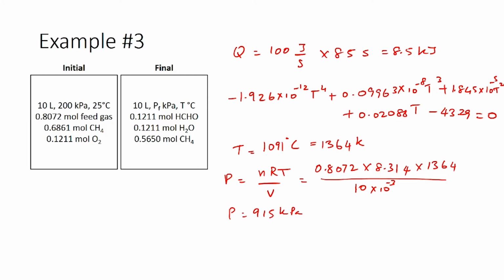However, in the second part of the problem, we have been told that the vessel explodes even though exactly that amount of heat is supplied. So, this is a problem, and we need to identify why that is the case. That is because you could have side reactions. The side reaction which you would observe would be a combustion reaction.